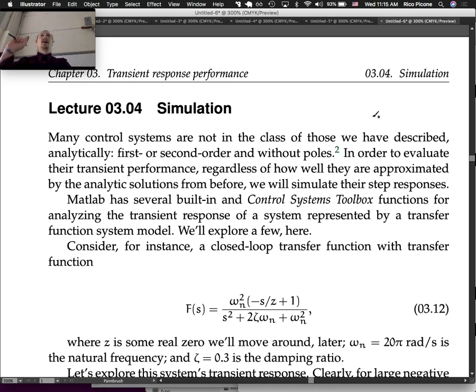We're thinking about design. We're thinking about changing a parameter to make it fit certain criteria, like settling time criteria. So we're going to want to look at the simulation at the end and say, okay, we need to maybe tweak something in our design to make it actually get there. So maybe we have a percent overshoot requirement of 10%, and it's actually 12% after we use the second order approximation. We might need to tweak something in our system to make it a little bit lower still.